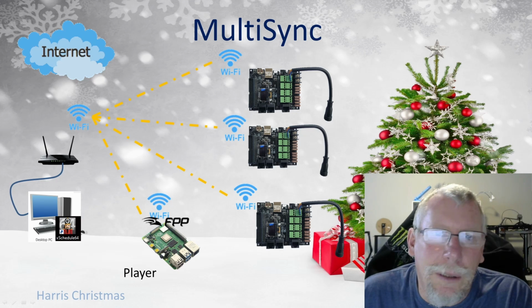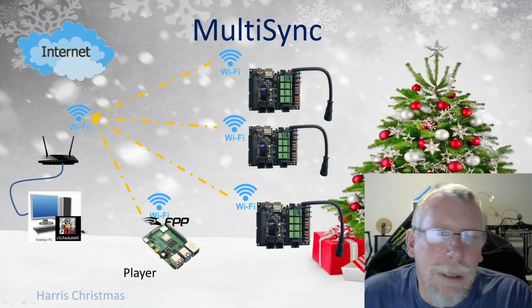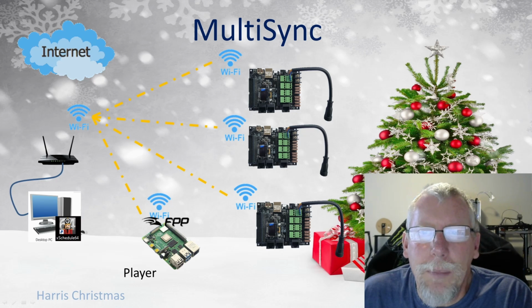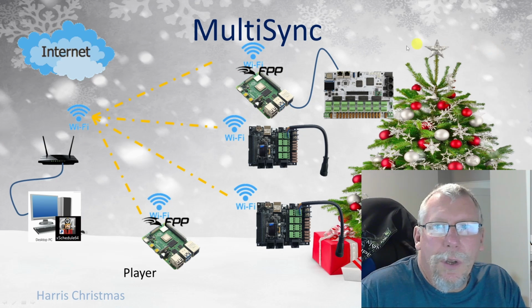This method requires a controller that supports a remote mode and Wi-Fi capabilities. The Kulp-like line of controllers works especially well with this method, but if your controller doesn't support remote mode, like the older Falcon line of controllers or other E1.31/DDP based controllers, you can still use the multisync mode. You'll just need to add an FPP device like a Raspberry Pi, and this is a common practice. So you could have it just configured with the Pi acting and then connected to the controller.